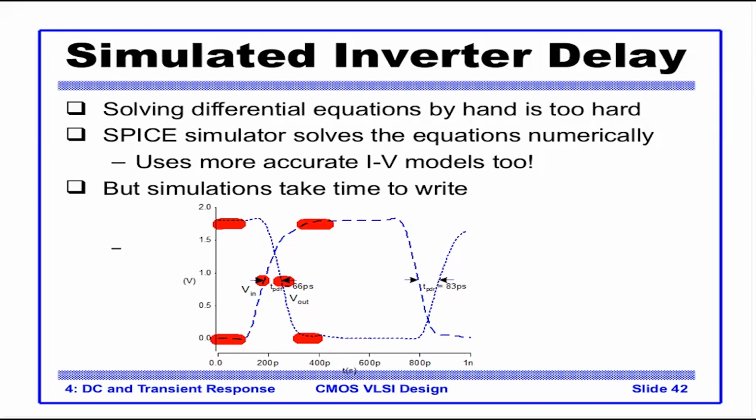I'll also show you the rise time and the fall time. The propagation delay refers to the difference in time between the output and the input when output is falling or rising. If you consider the VDD alone, the time it takes from this point, let's say 20% of VDD, to go to this point, let's say 80% of VDD, this difference here is nothing but the rise time.